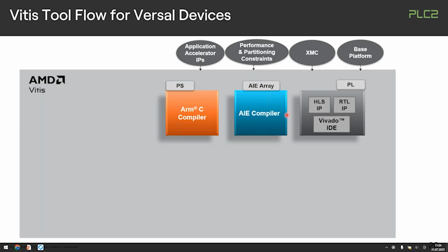And on the other hand, we have still the PL part to fill. And the very typical thing, if you are working from a software-defined context already, is that you are picking some higher level modeling like HLS. HLS would pick up your C function that you would traditionally run on your ARM core and will cast it into HDL code for you so that you will get the hardware to work for you instead of the CPU instructions.